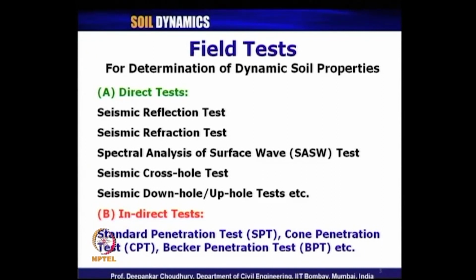Within field test, we have sub-classified mainly in two broad categories. One is called direct test, another is indirect test. Within direct test, we have seen seismic reflection test, seismic refraction test, SASW or MASW test, seismic crosshole test, seismic downhole, uphole test, etc. And indirect tests are common for static tests, field tests like SPT, CPT, BPT, pressure meter test, dilatometer test.